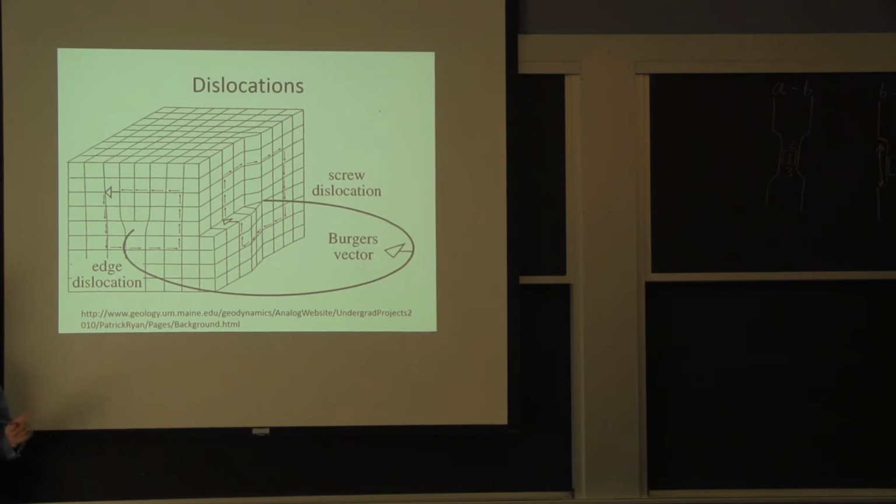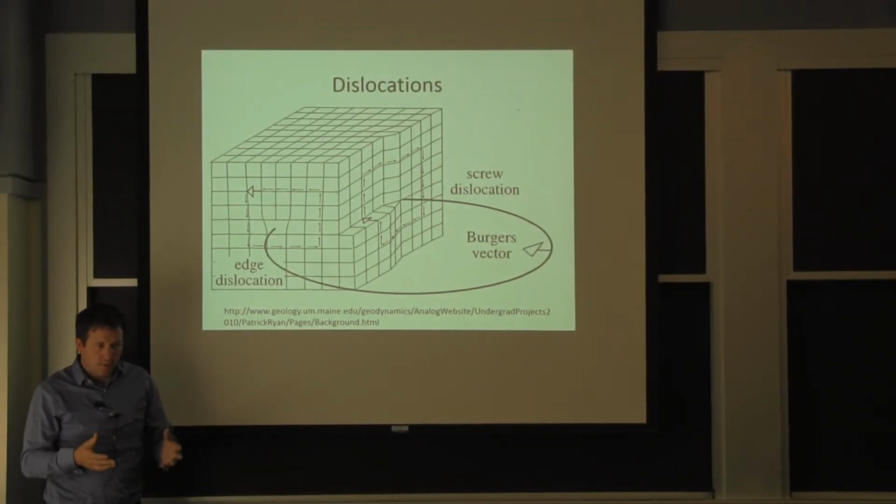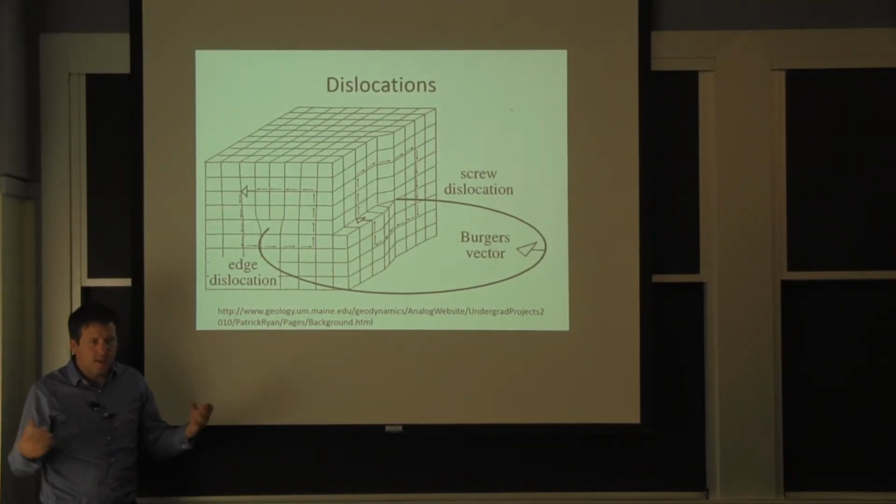Now, that's not how we create them. There'd be a lot of energy in making that displacement all at once. The way they actually create it is the Frank-Read source I showed, where it spins and just moves gradually, and it's so low energy. The only real obstacle to the dislocations helping deform the material is when they start hitting each other.